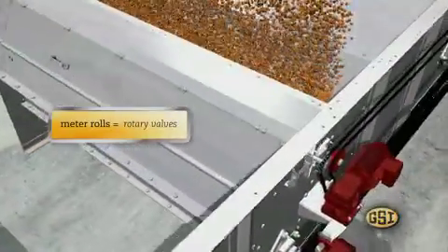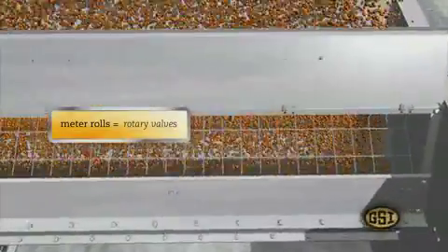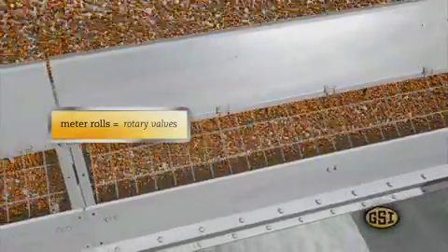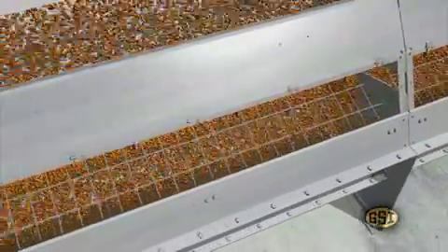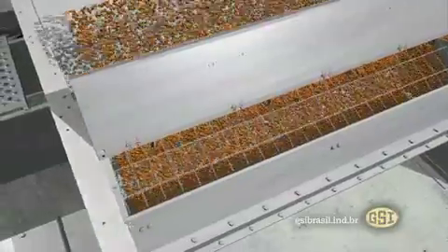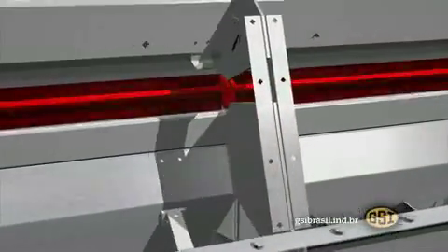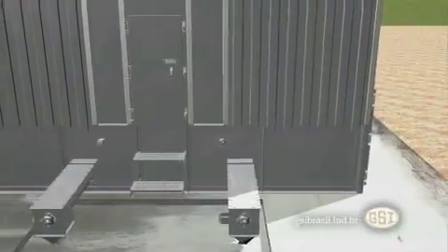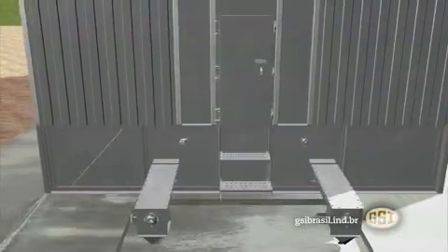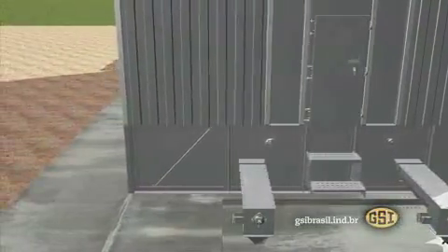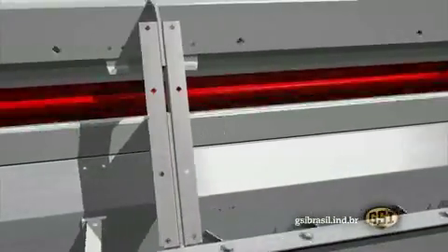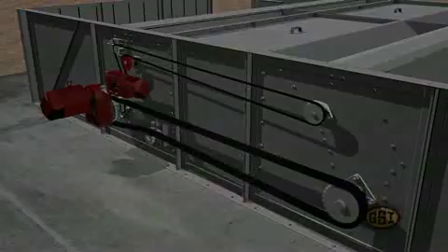The grain mass moves downwards at a constant speed, defined by the rotation of the feed roll at the base of the columns. The rotation of the feed roll is controlled by a frequency inverter, where the operator keys in the necessary rotation based on the initial and final moisture of the grain. An unloading system with screw conveyors is attached to the base of the dryer, simplifying this stage and reducing costs. The augers and screw conveyors are activated by geared motors.